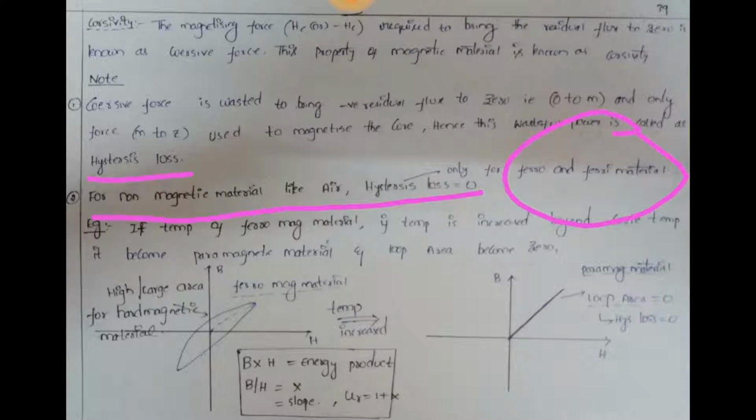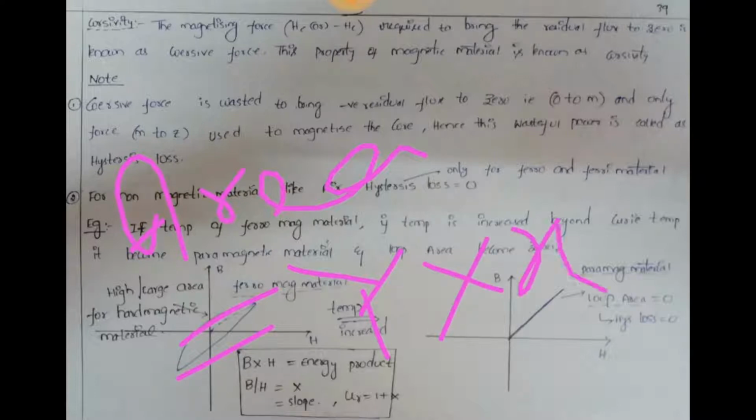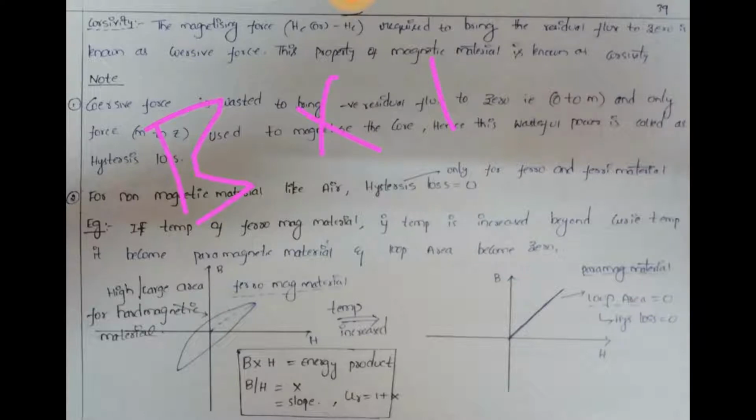Now you see, this is H, proportional to I, and mu, this is B. The area, how do you find the area? You have read in 10+2 standard, y into x. If you do the product, you will get the area. If you do B into H, as you read in EMF, B into H will give the area, that is the energy loss. This is a curve. Since it gives an additional power loss, when you do B into H, it will give a form of losses.